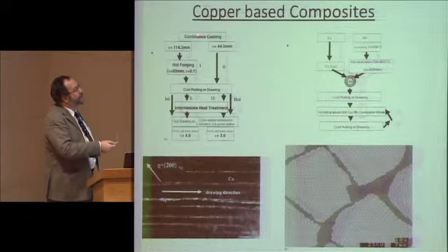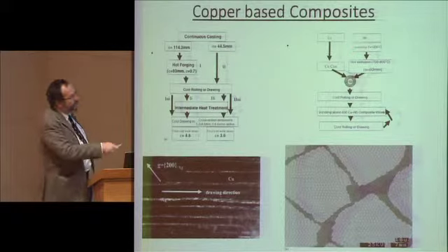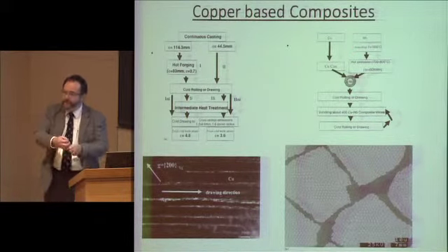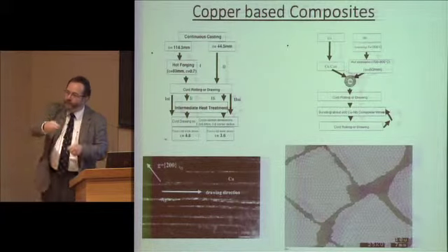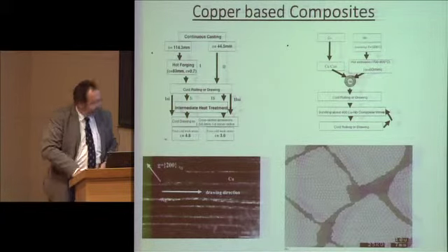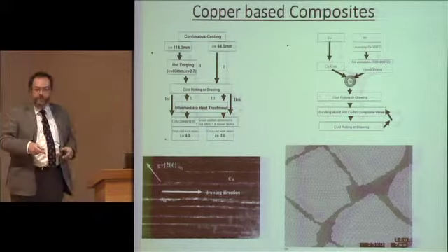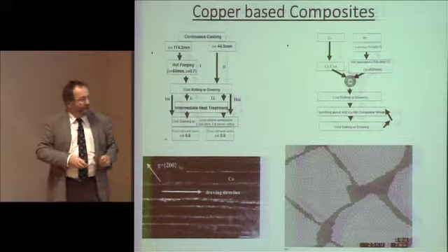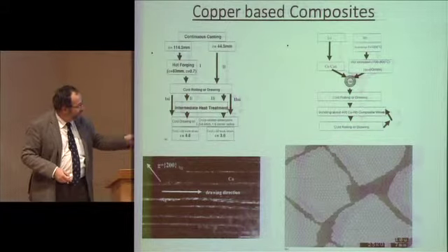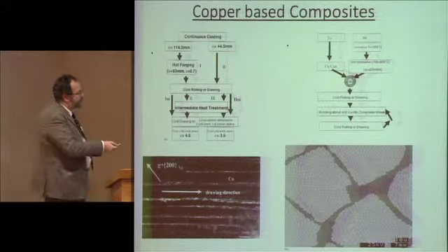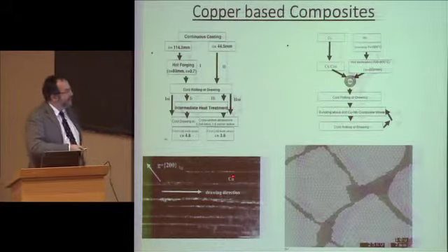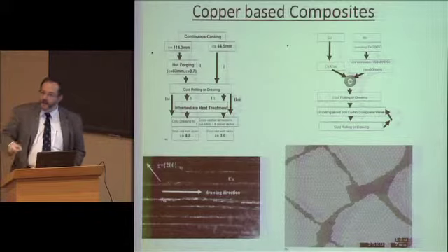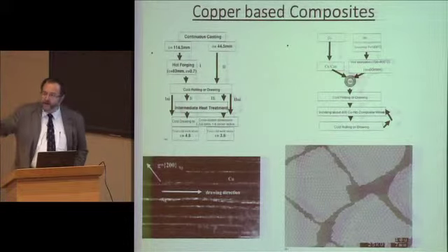You have a mold, you have solidification here and co-extrusion here. What you're doing is that you have copper wires, silver wires, put them into an extrusion machine, and you start again and again and again. You have this superb structure, which is wire, wire, wire, wires, and you can do it as often as you like. You have here 50 nanometers, it's very small,